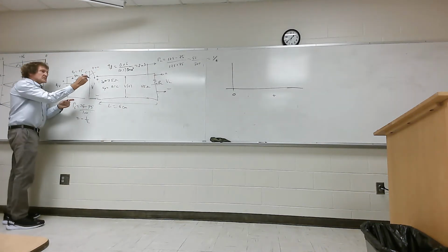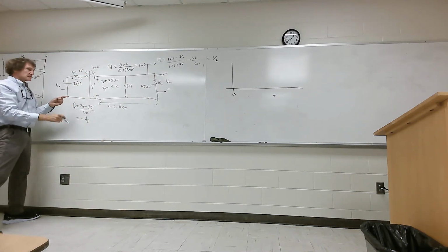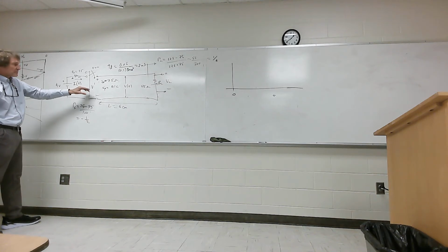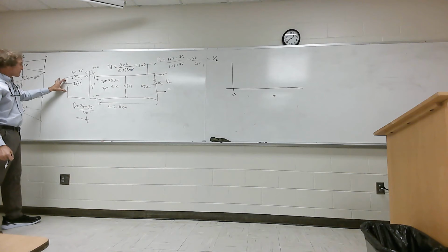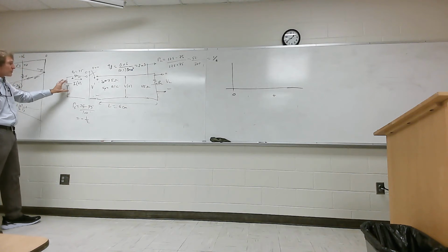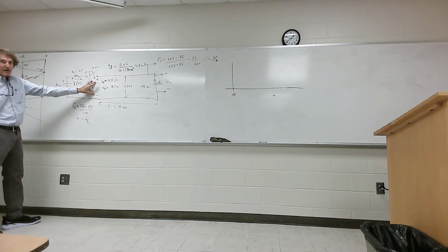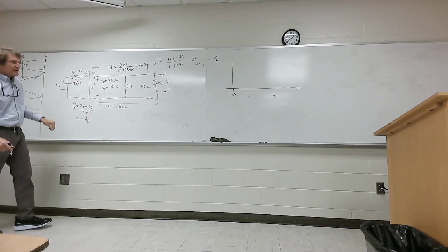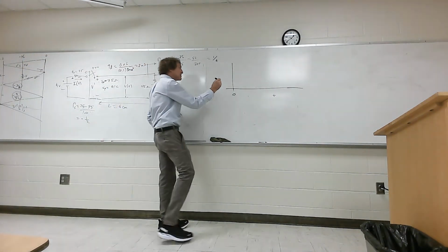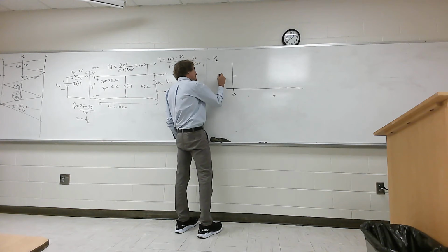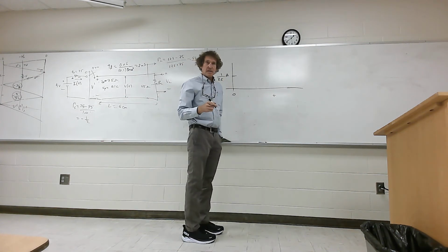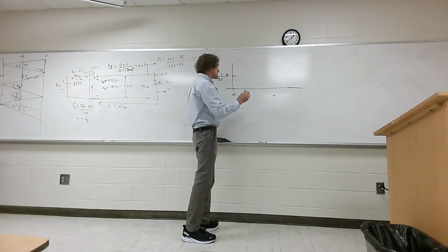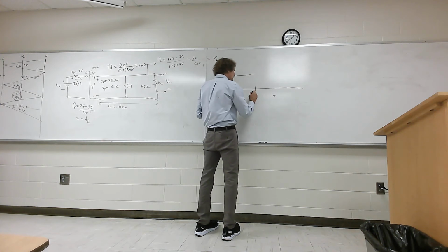I know the voltage here, just as that switch closes, it's basically voltage division at that point. But I have 3 volts here, do you remember that? And I have 4 volts here, so the initial current would be 4 minus 3, or 1 volt divided by 25 ohms. So the current initially would be simply 1 over 25 amps. All with me on that, class? And the reason is you want the voltage across that resistor. Now that's going to stay that way.